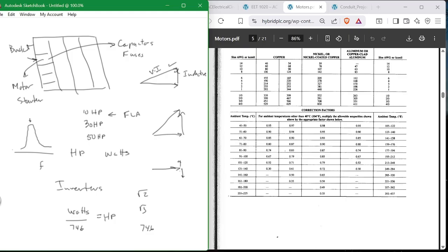You use the idea of cancellation of the X sub L and the X sub C, and you minimize the R, and you pick it off. It's called a high Q or a quality factor circuit. High Q circuits are circuits that can pick off one frequency at the expense of all the others and give you a high peak.